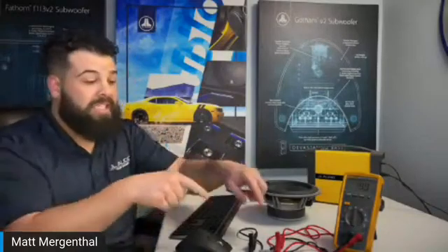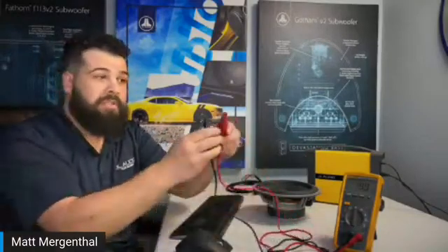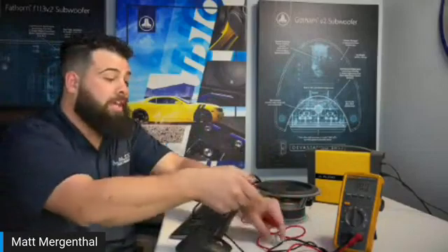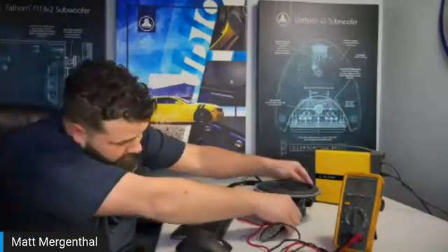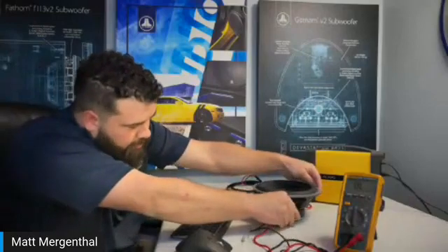You can see it fluctuates back and forth. So that's the DC resistance of this resistor. Now I can measure the DC resistance of this speaker. If I clip these terminals onto the speaker, we can see that our DC resistance is just under 4 ohm. Looks like it's going up and down slightly, between 3.8 and 4.